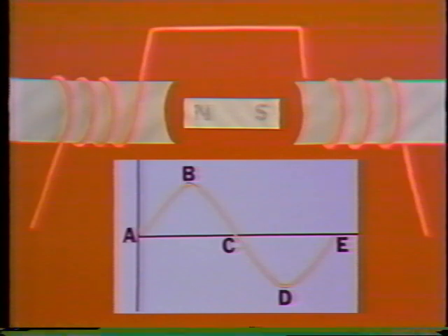When we first apply it to the winding at A, there's zero current, so no field is developed between the stator poles. Now, in the time between A and B, the magnetic field builds up as the applied current does. The stator starts developing magnetic poles.